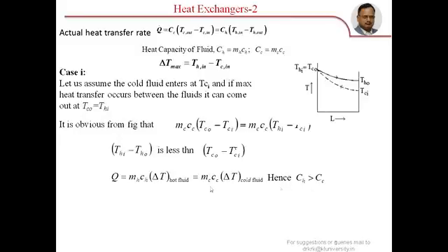Catch the point here. The hot fluid is subjected to a low temperature difference. The cold fluid is subjected to a high temperature difference. The product should be equal. By the lever rule, the heat capacity of hot fluid should be greater than the heat capacity of cold fluid. Hence, CH must be greater than CC.